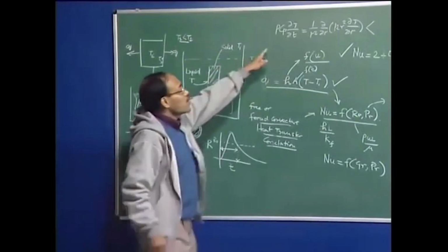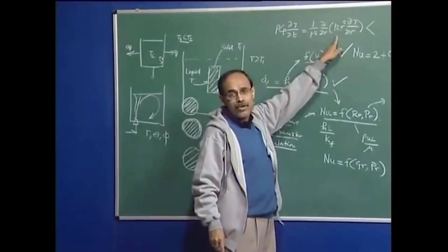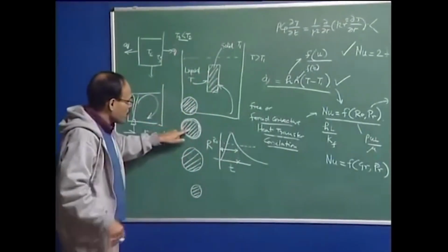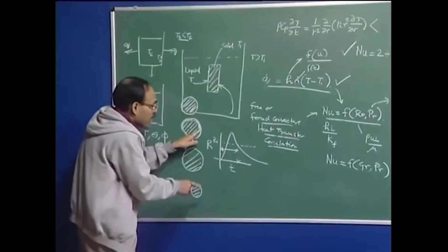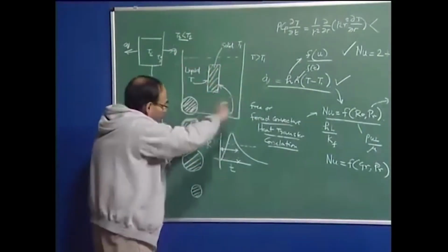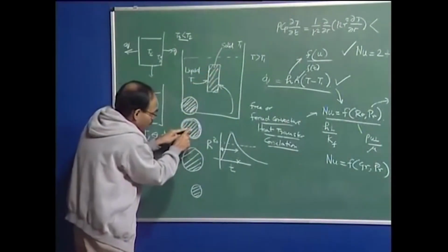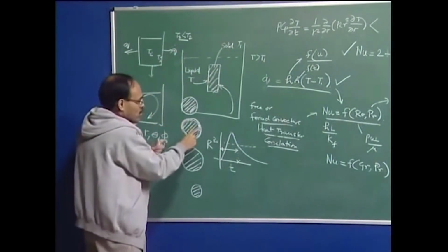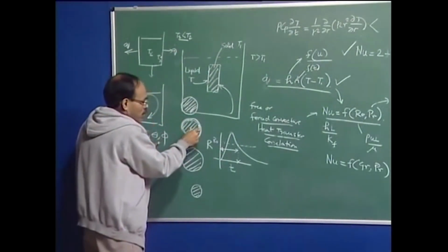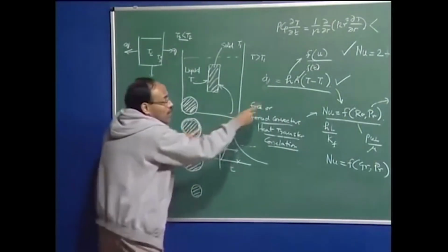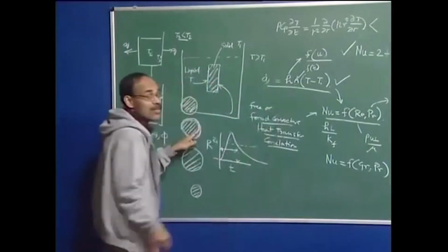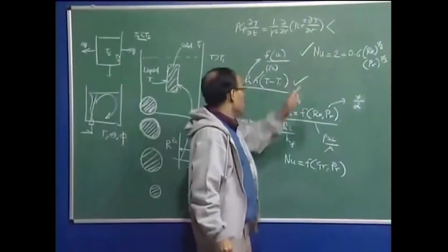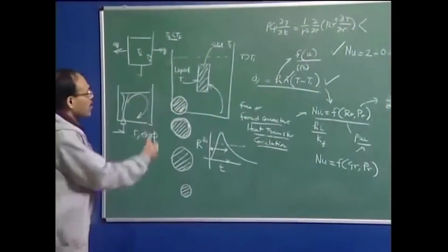Note that in the first equation, no information is there on the fluid flow itself. How does the fluid flow part get into the equation or the process mathematically? It is because at the surface, I require boundary conditions. So, for example, at r is equal to r1, which at a particular instant is the radius of the object, the rate at which heat is flowing can be given in terms of the heat transfer coefficient, which is the convective heat transfer coefficient. So, through the boundary condition, I will be able to incorporate the effect of fluid flow.